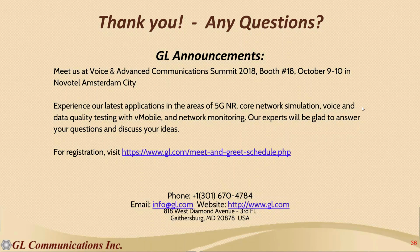That voice is going to be put onto the packet. The packet statistics are going to show excellent scores because you're not going to be missing or losing packets or jittering packets, but the actual voice, the MULAW voice or the G729 voice inside the packet, is possibly not going to be intelligible.